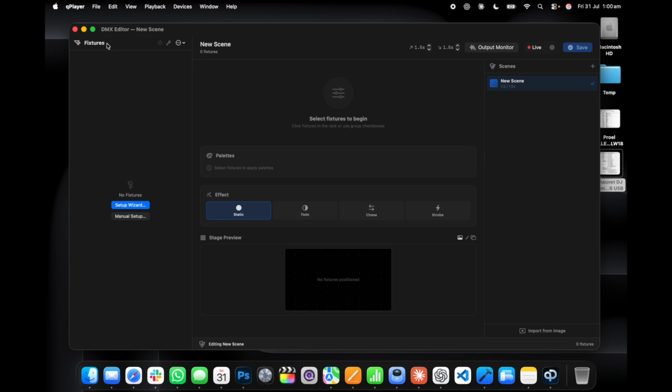First of all, you'll have your Ethernet port connected to your DMX interface, your ArtNet interface. For this demo, we're using the Chauvet DMX AN2, which is a very cost-effective unit. It works very well, and it's got a couple of universes. How it ships by default, with a certain IP address and subnet mask, is very important with how we set up our computer. We'll put the details on the screen.